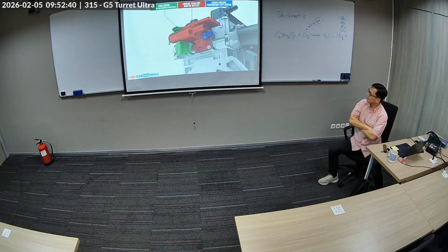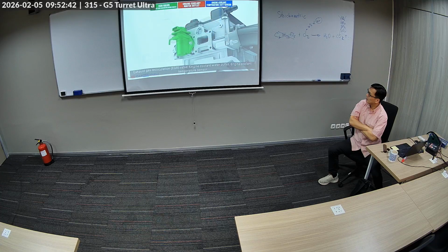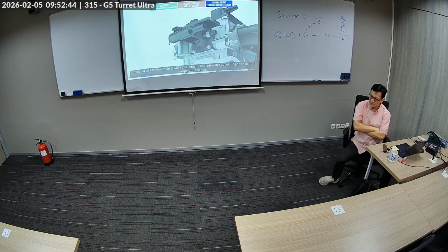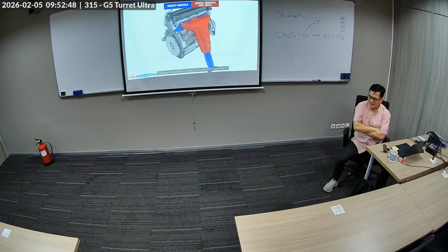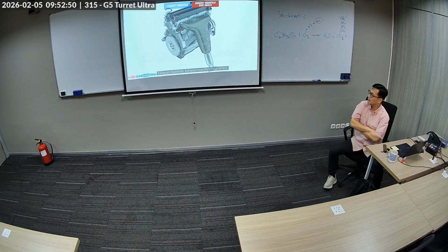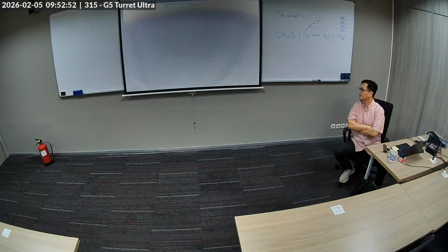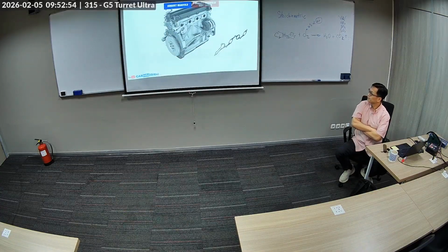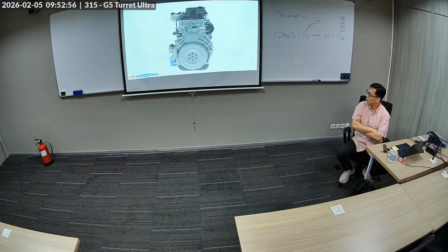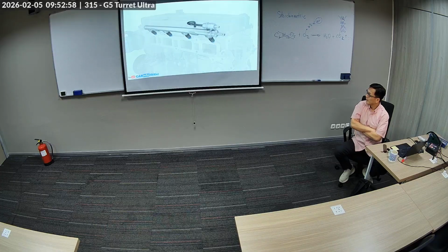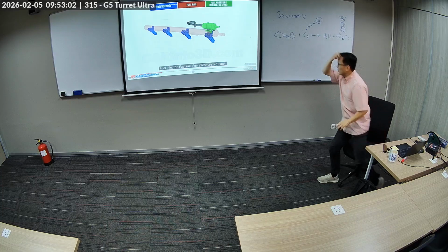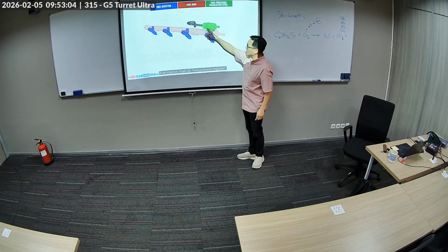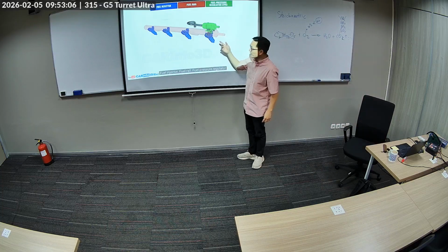Yeah, this is a very nice assembly of EGR, exhaust gas recirculation. It actually helps the combustion a bit by mixing in combustion products. Exhaust manifold. There's your injector, the fuel rail. This is the regulator. I think I mentioned it before.